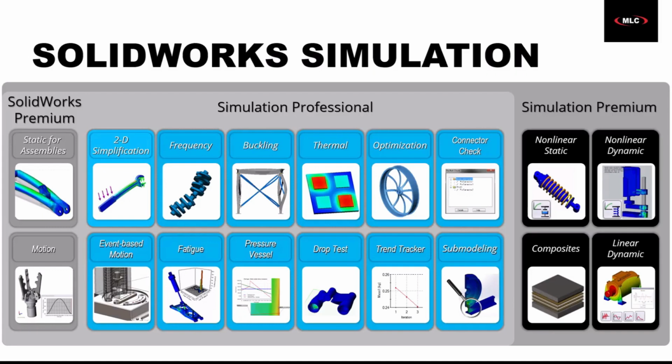We can refine the mesh, do whatever we need to do, but it's going to take all of the displacement inputs on the edges of this cut material, and from the large assembly, it's going to apply them to the submodel. So we still get accurate deflections, but now since we have a much finer mesh, we can get much more accurate stress results without having to wait hours or days sometimes to get an accurate stress.